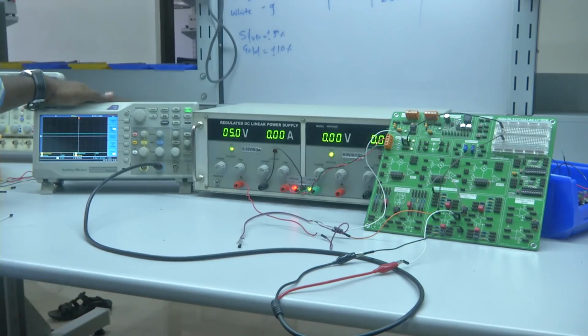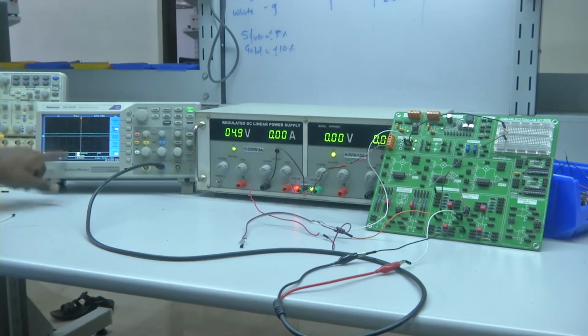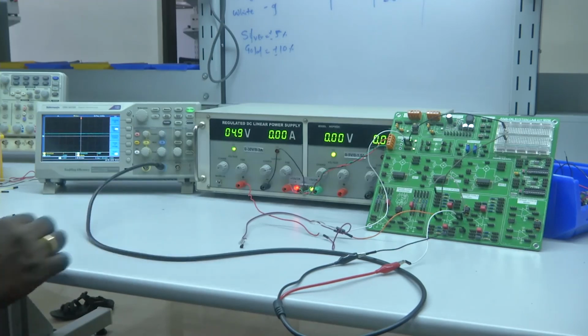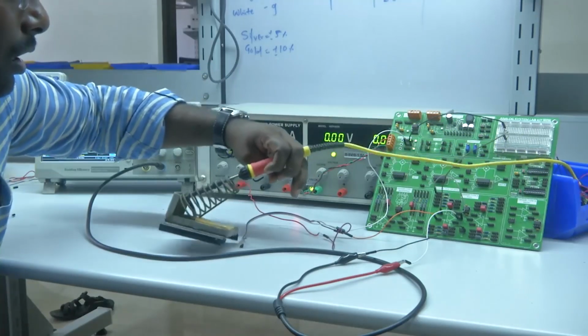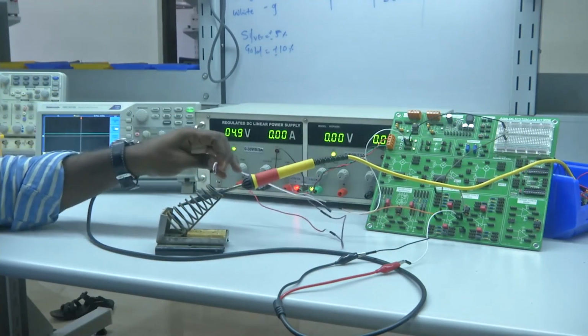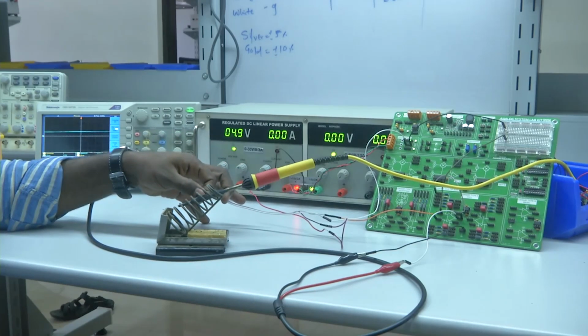If you recall, the room temperature that we measured was close to 28 degrees. Now, the mean value is showing 2.6 volt. Previously it was 2.8, now it is 2.6. The difference is because of the difference in the gain. There is an error of 2 degrees, but let us observe the working of this LM35 by just probing, touching it to the soldering station, to see whether we get the same temperature or not. So, I just connected it.